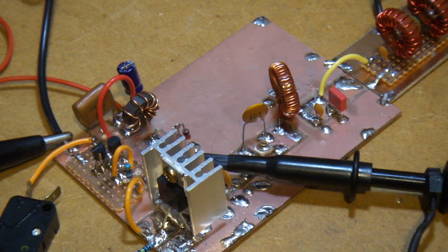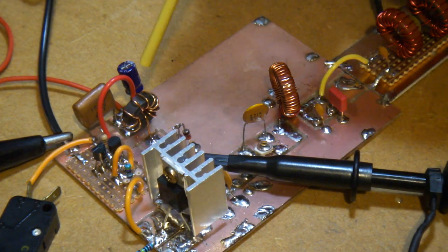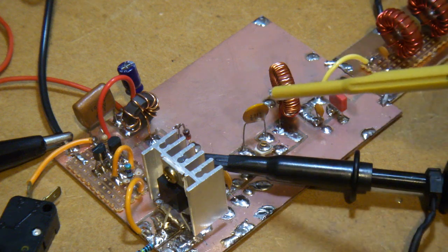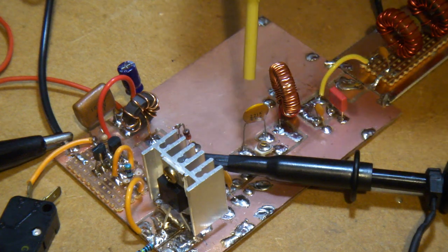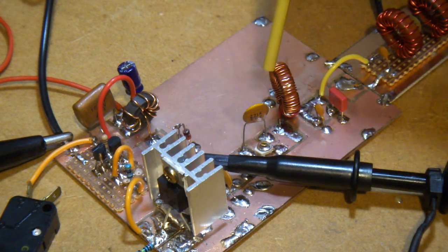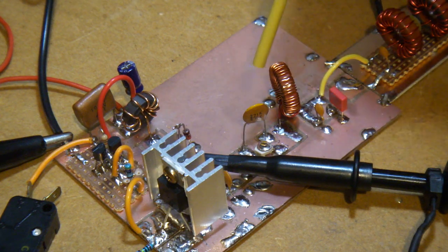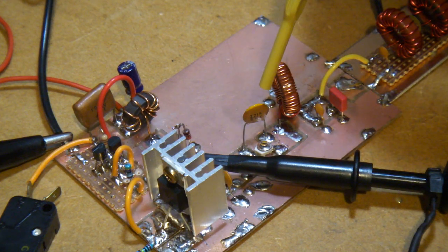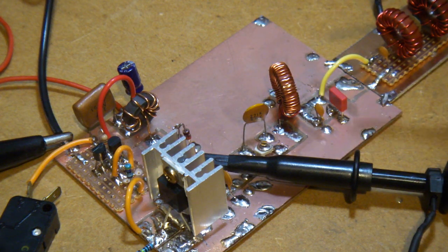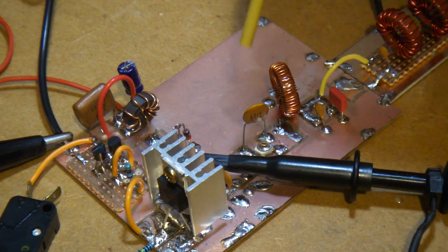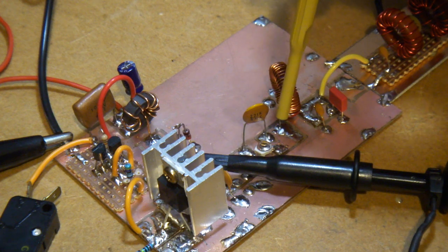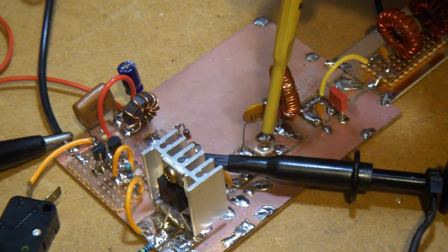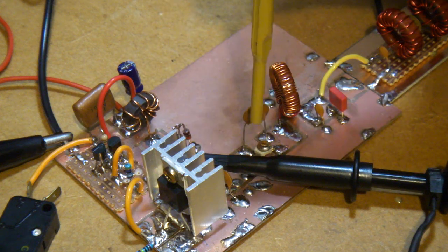So, what else is worth discussing here? And we'll see it in action in a sec. In the end, that C series, it wanted to be 271 picofarads. I built the amplifier and tested it, and through a little bit of trial and error I reduced that, so I've now got sitting there a 220 picofarad capacitor in parallel with a small trim capacitor which has a maximum capacitance of 54 picofarads, which gave me the ability then just to tweak that value there.